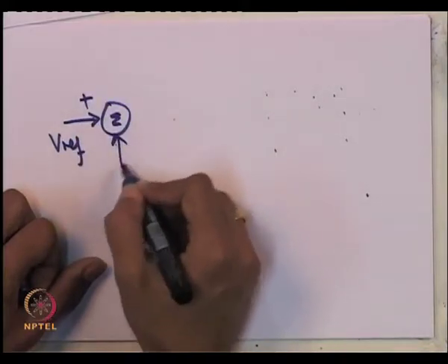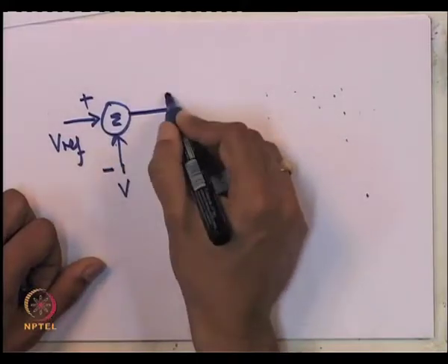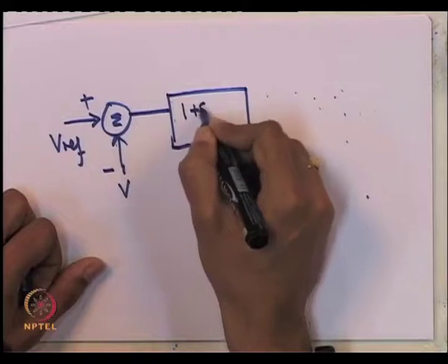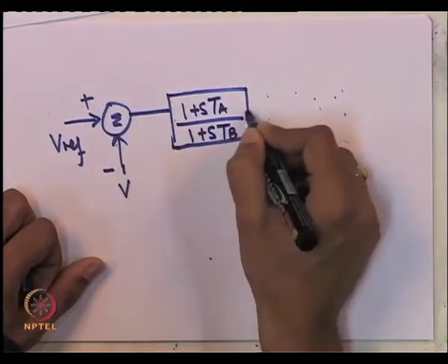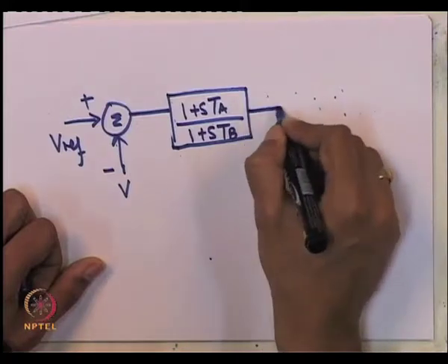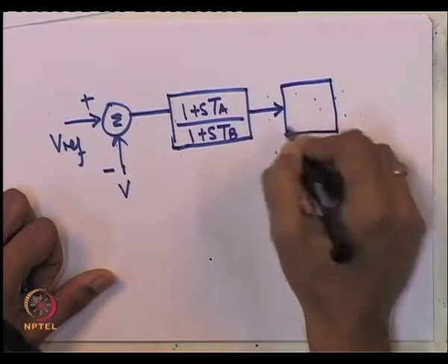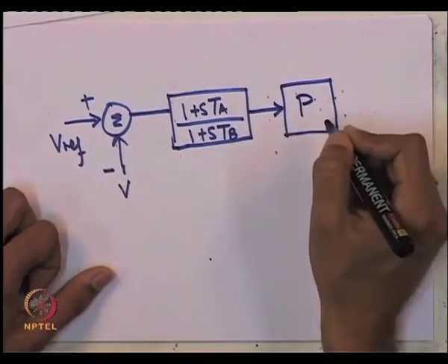this is the summing junction of course, then you have got a lead or a lag block, you could have a cascade of these, you could have another for example, if you require it, if your time response has to be further tuned. Then you have got a PI controller, but usually a high gain P controller suffices.